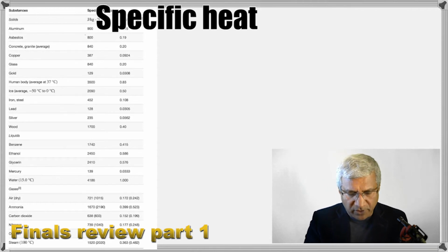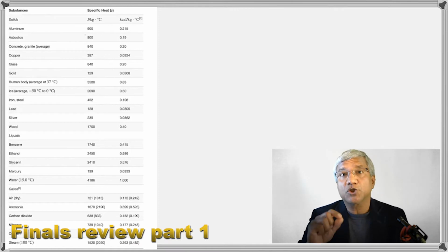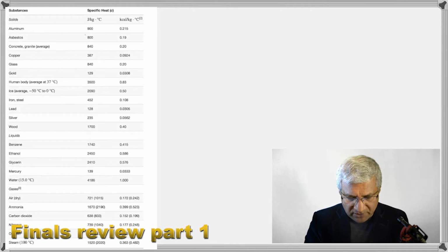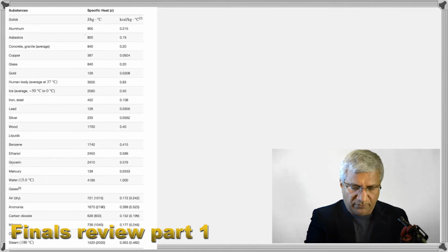4,186, okay? So we look at that left column, which is in joule per kilogram. You see aluminum has that 900, then copper is 387, like I told you. And you come down, the human body is about 3,500 at 37 degrees Celsius. So these specific heats depend on temperature, but we're not looking at that part. Water down there, you can see, is 4,186 and so on. So if the specific heat is big or it's a large number, the substance cools and heats slower. If the specific heat is small, it gets heated up or cools down faster. That's what you got to know.